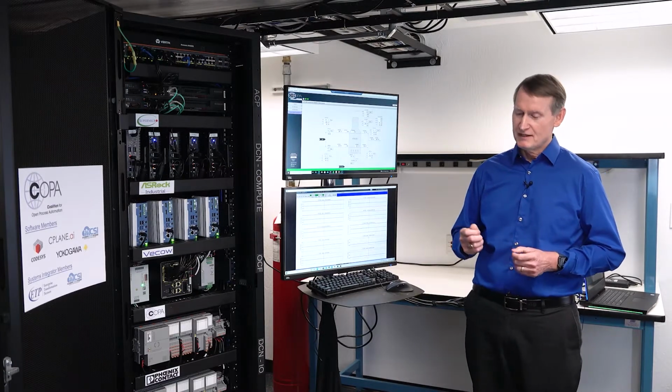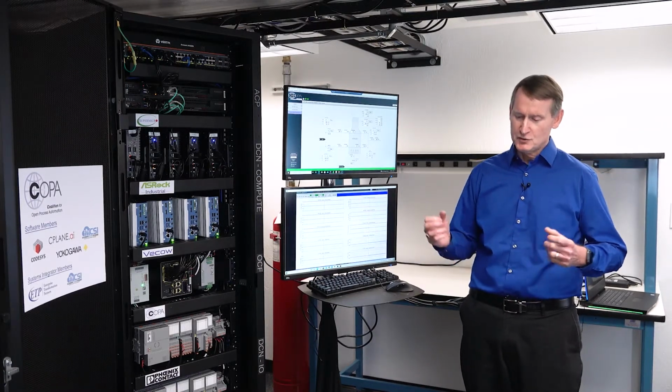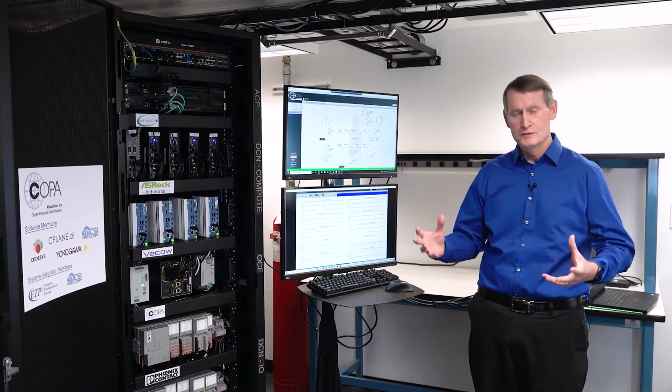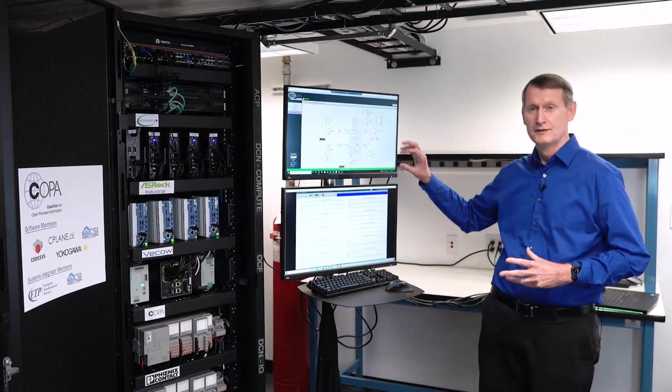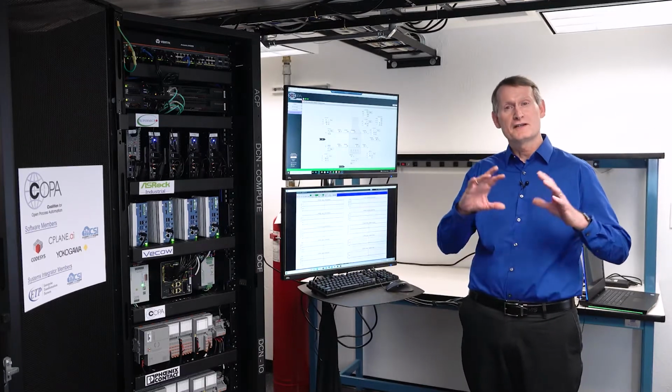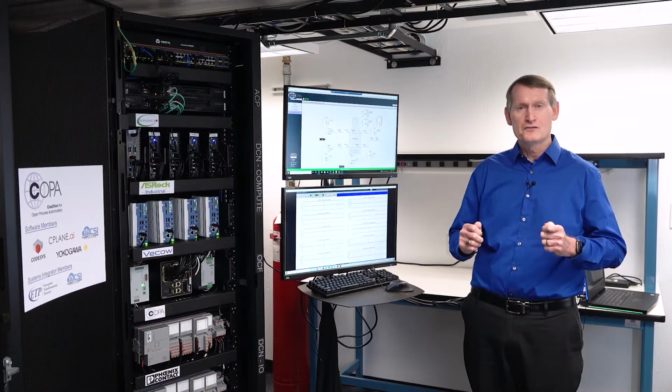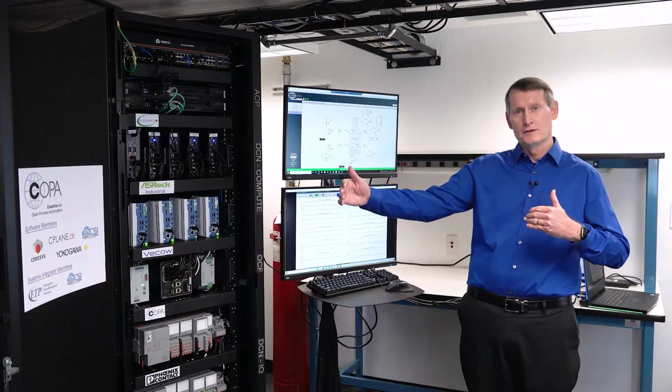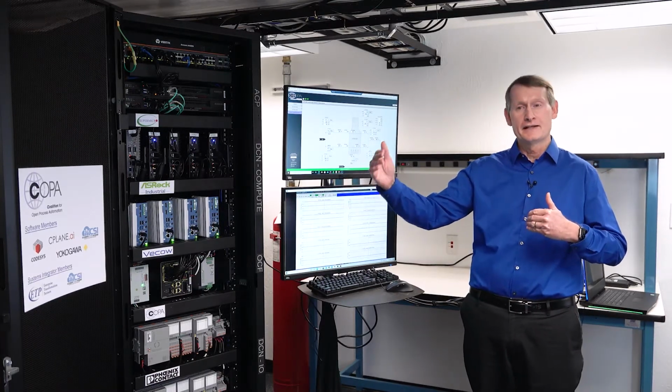The difference is that instead of individual controllers that are trying to cooperate, you develop a single mathematical model of a whole system, in this case, this whole fired heater. And you hand that over to the control algorithm, and that gives the control algorithm a holistic view of the entire unit. Using this model then, it can see the effects of everything on everything else, and it can predict out into the future, so it can anticipate things that'll happen, like hitting constraints in the future. So this technology has been very successful, particularly in chemical plants and refineries around the world.